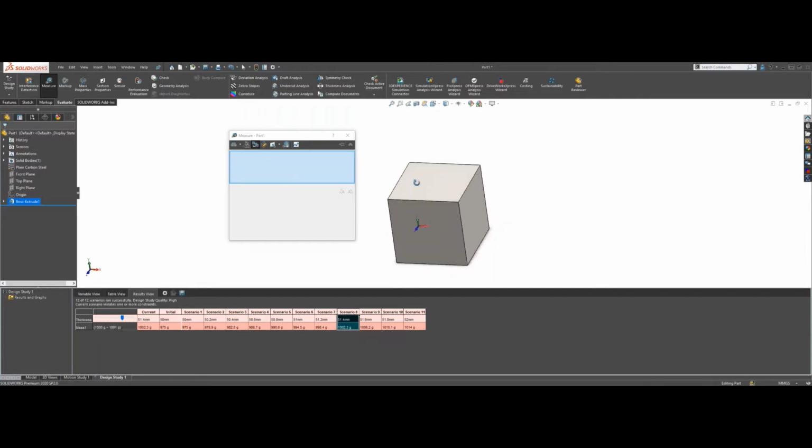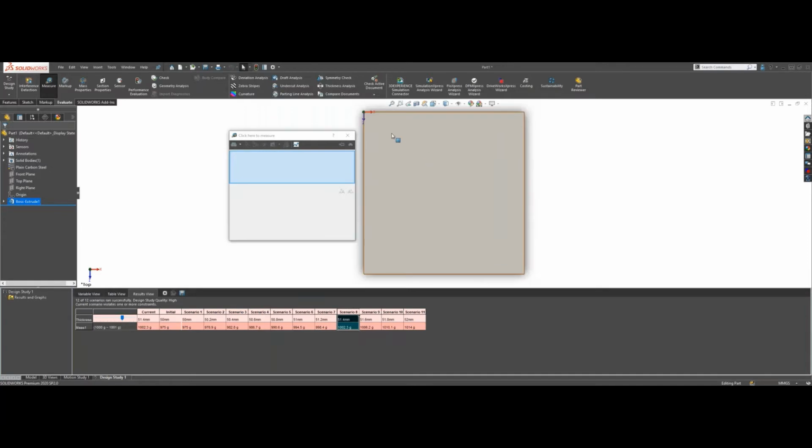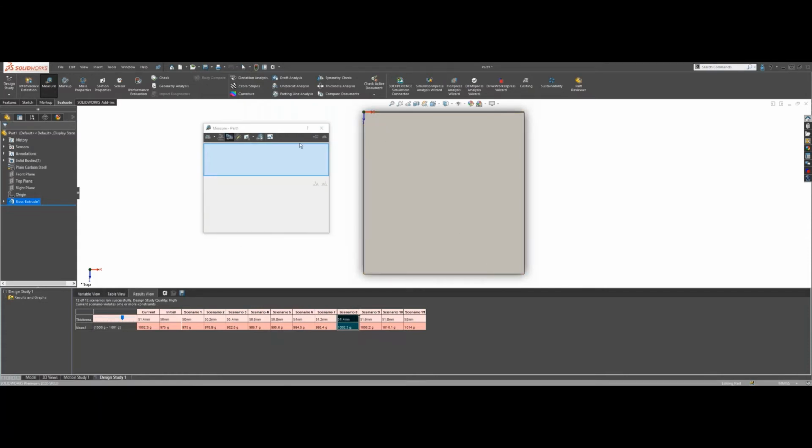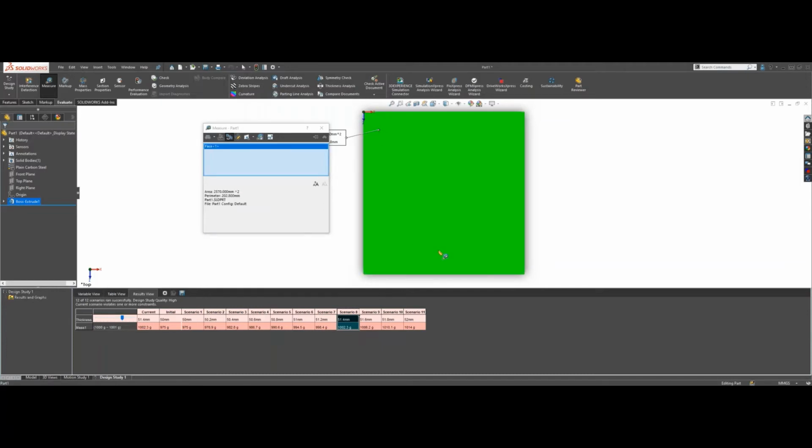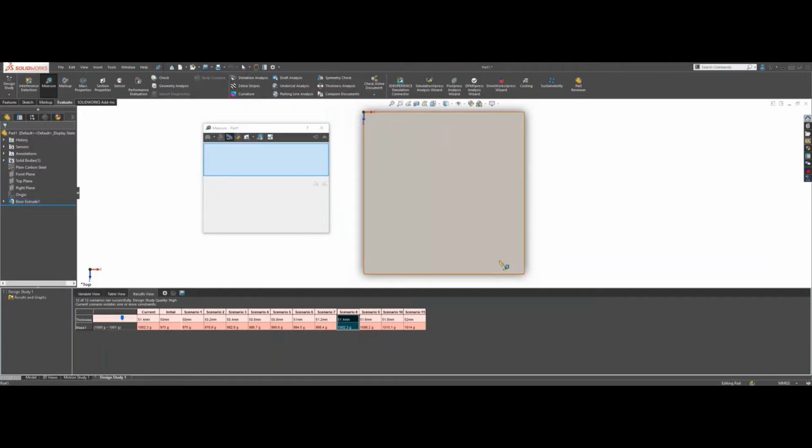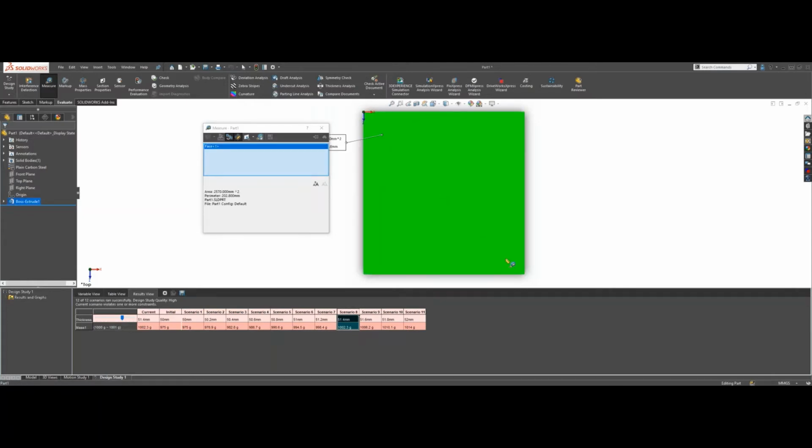All right, so I'm going to make this here normal to me. Okay, so what if I just want to measure a point from this end right here to this end? Well, you can see that if I select the face, right, and I say from that point to this point, it just selects and unselects the face, right? And that is due to the fact that I don't have the point-to-point selection. Now when I do the point-to-point selection, whenever you do a left click, it's going to tell you, okay, well, you have your DX distance, right, your DY distance, and your distance right here as well, right? The one that you can have.